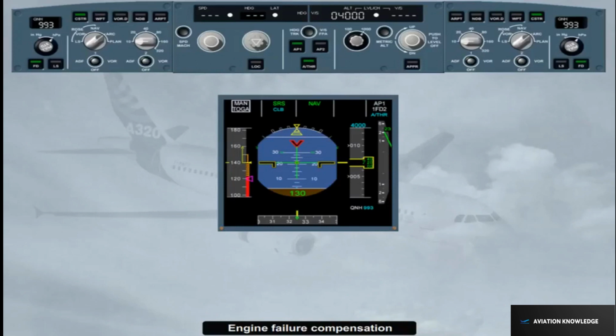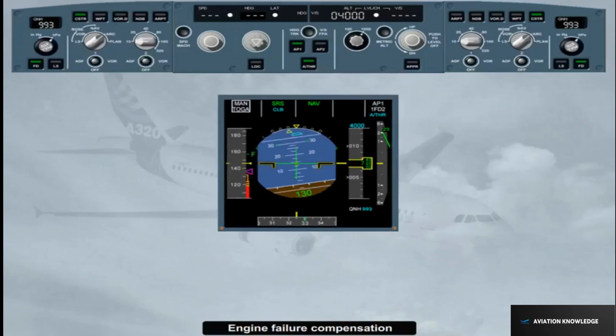In case of an engine failure with autopilot on, the FMGC ensures an automatic yaw compensation in all modes. This is achieved by the FAC, using the yaw damper at takeoff and go-around and the automatic rudder trim in all modes. Furthermore, the autopilot flight director speed reference system pitch mode automatically adjusts the reference target guidance speed in case of an engine failure at takeoff or go-around.